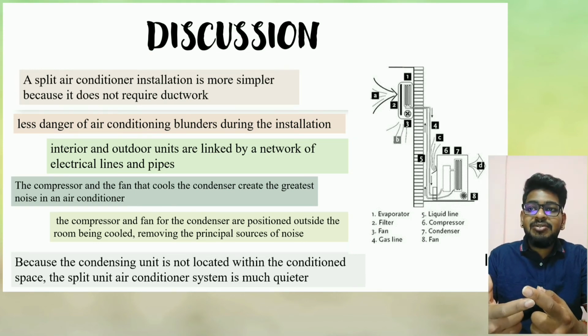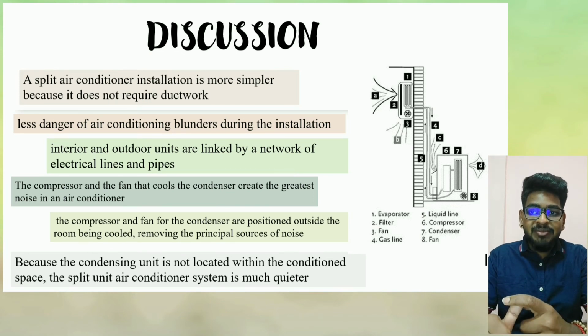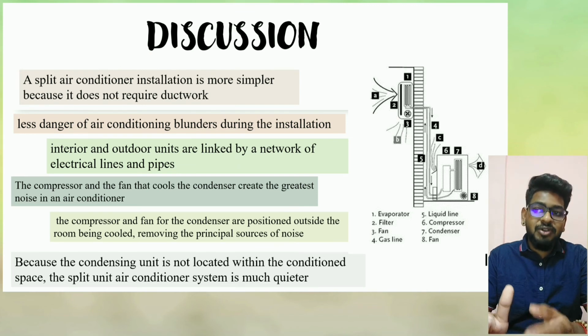One apparent advantage is the silent operation of a split air conditioning system. The compressor and the fan that cools the condenser create the greatest noise in an air conditioner. In a split system, as opposed to a window unit, the compressor and the fan for the condenser are positioned outside the room, removing the principal source of noise.